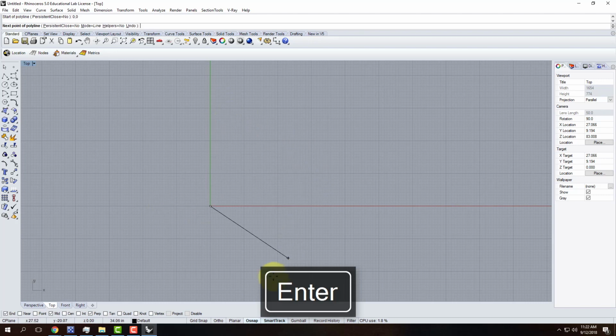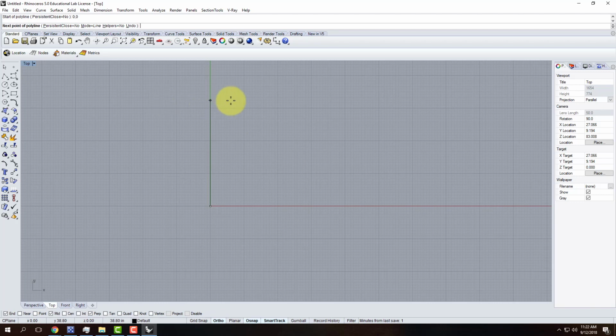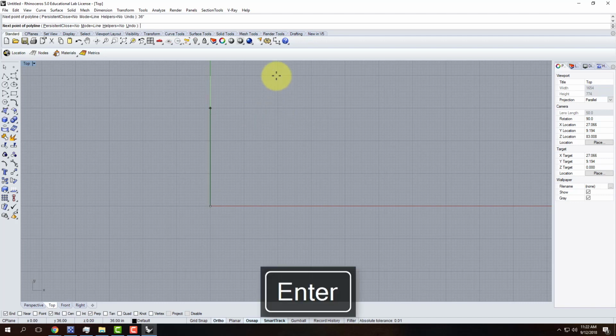And there we go. I'm going to go ahead and turn on ortho so that I stay in a line as I start to create this. And I'm going to go up by the first dimension, which was 36 inches, though technically if this was code, it would be 42. But I did this before the code changed, so it is what it is. So we'll do 36 inches. And there it is. So I've drawn that first straight line.